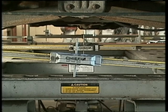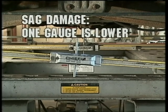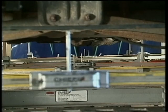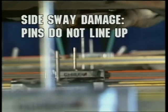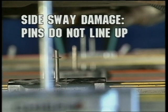Sag is a condition in which one part of the frame or unibody is lower than normal. Sag damage will show up when one gauge is lower than the others. Side sway damage exists when the front, center, or rear portion of the vehicle is out of lateral alignment. If a centering pin on any single gauge doesn't line up, then side sway damage is present.